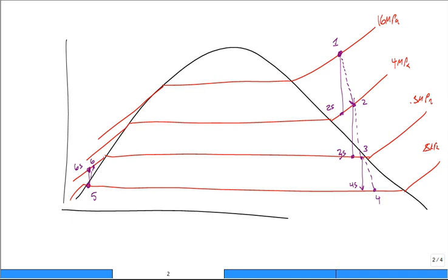Now, that's out of the pump. That goes into the feed water heater. What else went into the feed water heater? Some diverted at state 3. True? And then also some that came after the steam trap. Okay, let's do this now. We're state 7. It comes out of that feed water heater, right? What pressure is it at? 0.3, and it's saturated liquid. There's state 7. True?